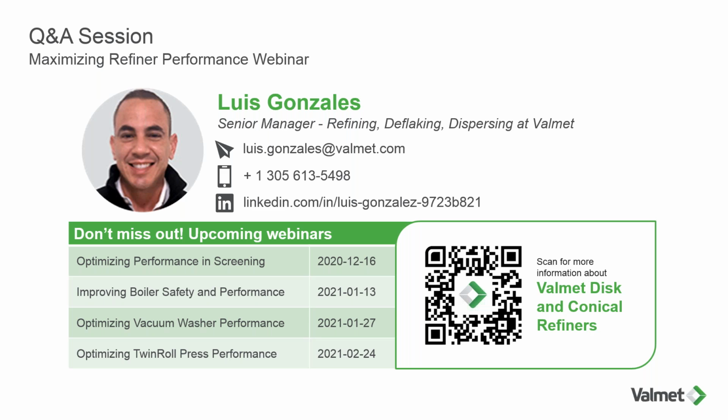On the process side, we collect a lot of the information before we get to the mill. So we're asking for things like flow, consistency, applied power, inlet and outlet pressure, plate designs. Then we come up with a report that indicates where you're at today on the process side with your existing equipment and where you could be if you optimize by, say, upgrading to spline technology, changing out refiner configuration, changing out refiner plates, stuff like that. And that will take us probably about a week to gather all the information.